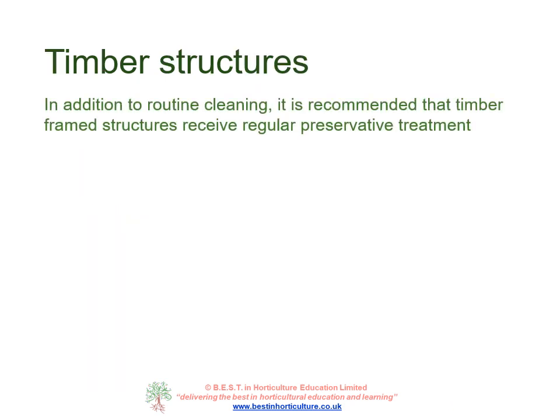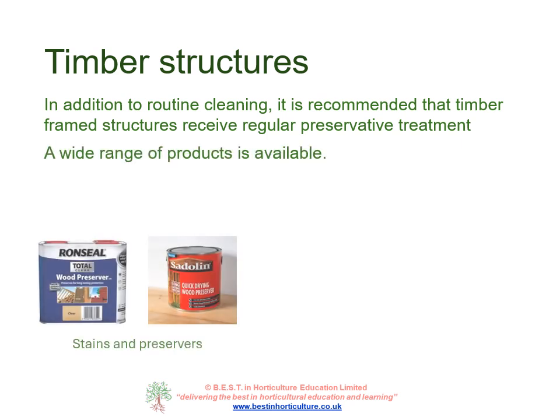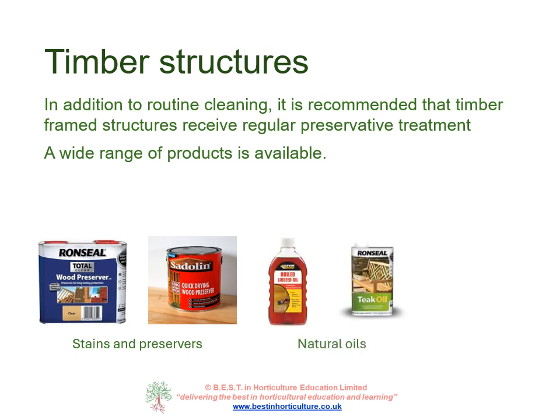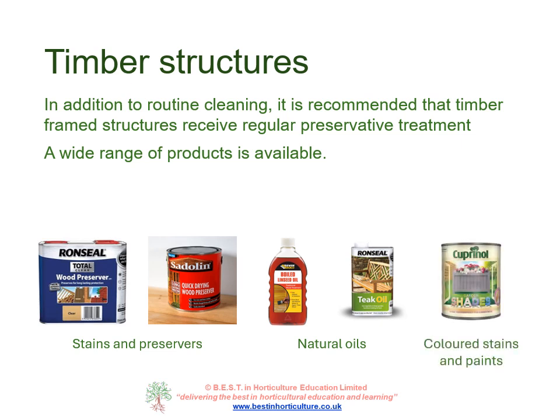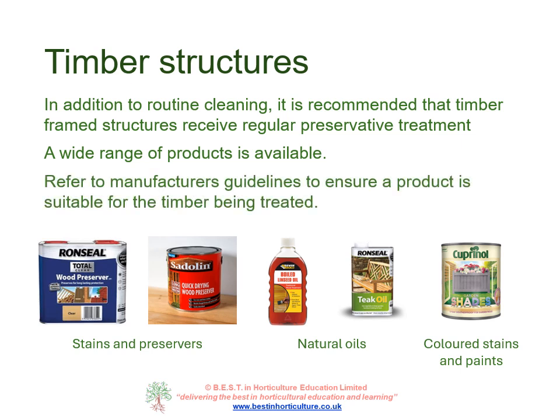Timber structures. In addition to routine cleaning, it's recommended that timber frame structures receive regular preservative treatment. A wide range of products is available, including stains and preservers, natural oils, including linseed oil and teak oil, and a wide range of coloured stains and paints which are particularly appropriate to domestic gardens where colour themes and effects are required.